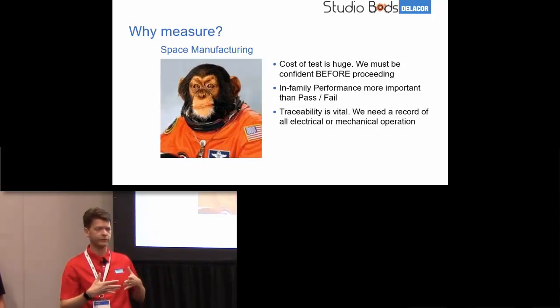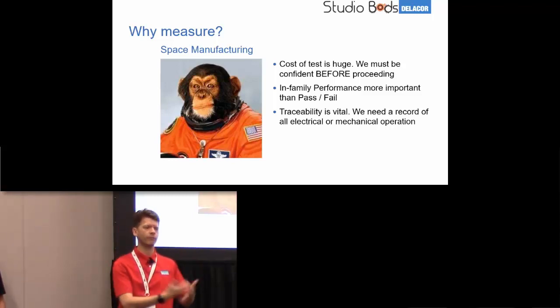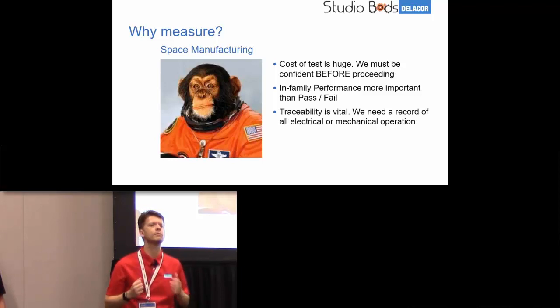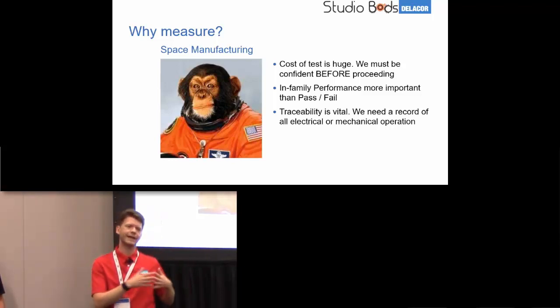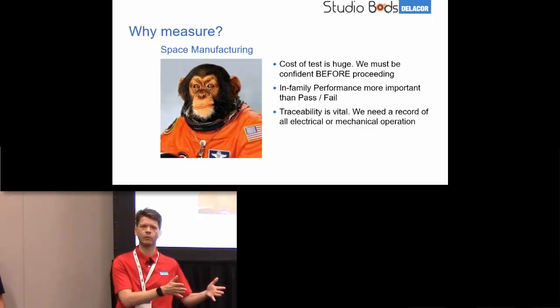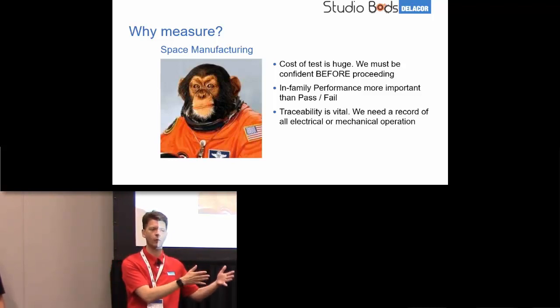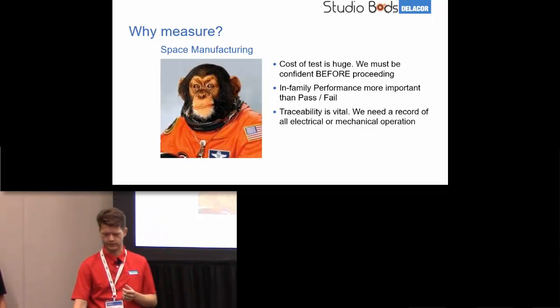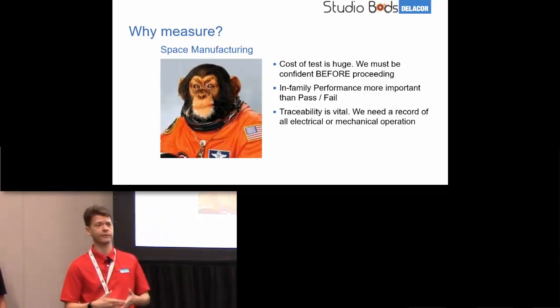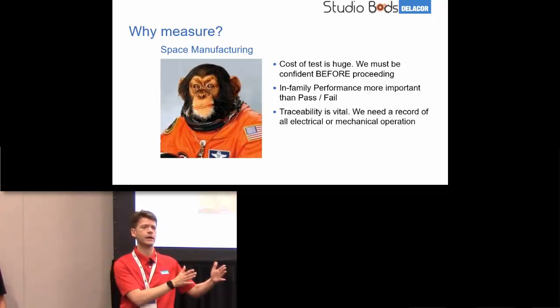And in the space industry, we simply don't have those obvious pass-fail criteria that we might have in other industries. Often we care about in-family performance. We don't care about an absolute limit, we care about how a device performed with respect to other devices in test. And then traceability is vital. We need to understand every test and manual process operation that was performed.